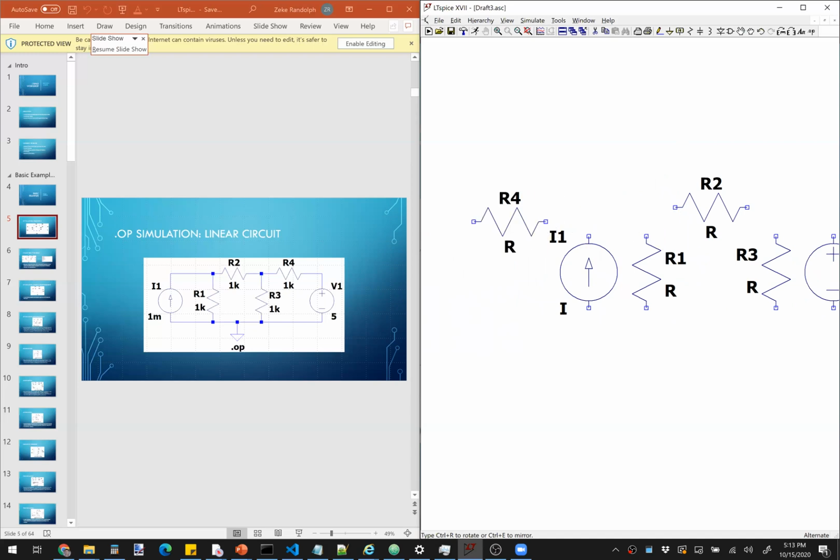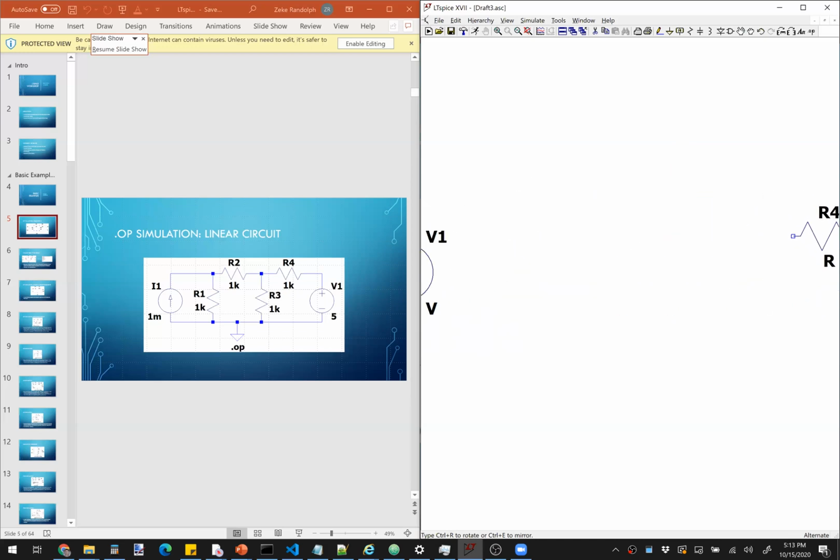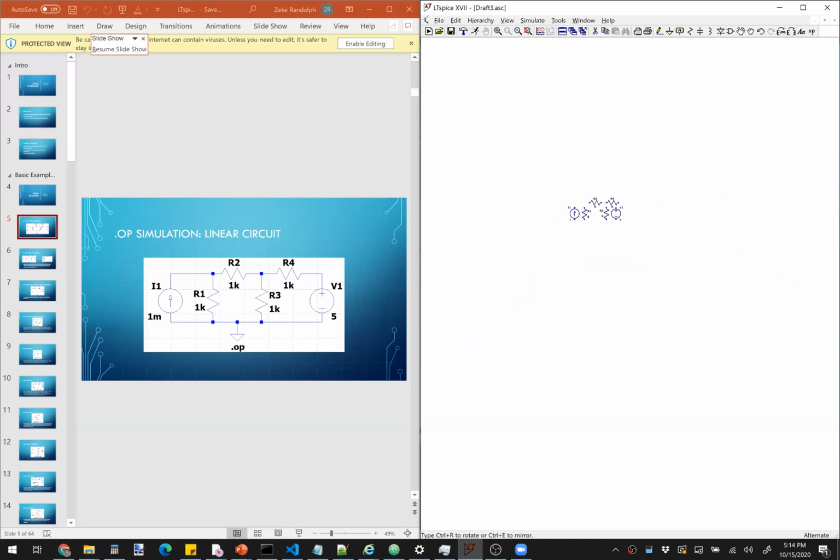I'm kind of shoved over here on the schematic a bit, and that's kind of inconvenient. I want to move to the right a bit. If I drag my mouse to the right, it moves me along the schematic. Another approach is you can use your scroll wheel to zoom in and out. So if I zoom out, then move my mouse over where I want to zoom in, and scroll to zoom in there, that's also a way I can reposition the schematic on my screen.